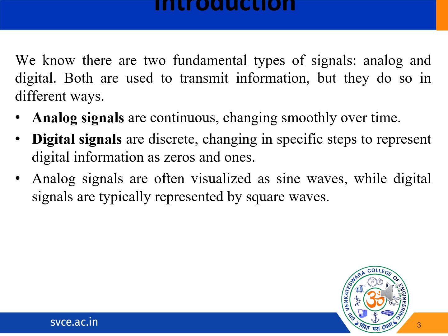So analog switches are designed to pass or isolate analog signals. So they essentially route analog signals based on a control signal. So analog switches can exhibit decent performance with digital signals as well. So they function similarly to relays, but without any moving parts. So they are also known as bilateral switches because they allow signals to pass in both directions. So analog switches are available in various packages. So it includes through hole and surface mount technology.